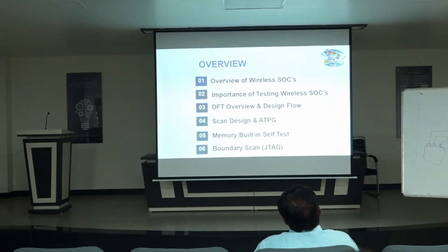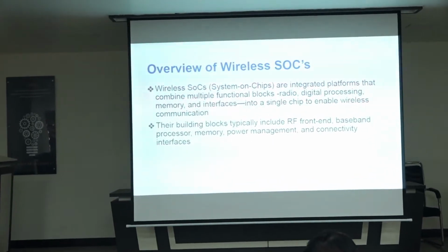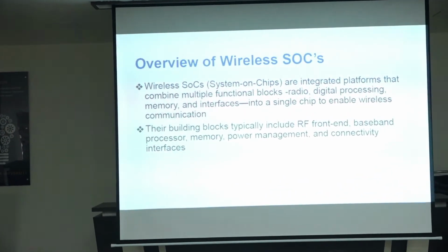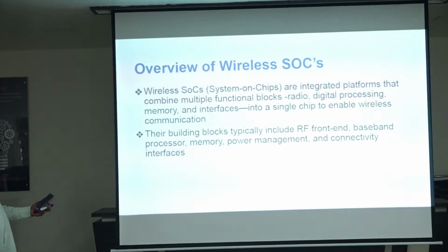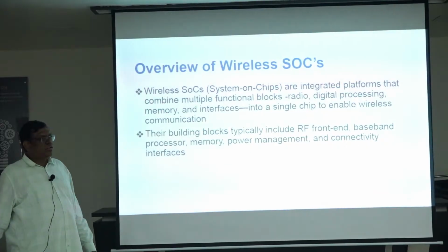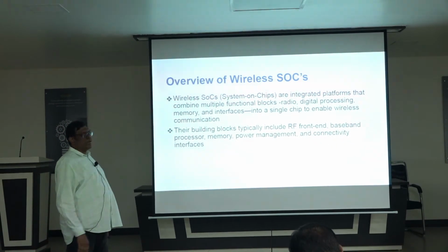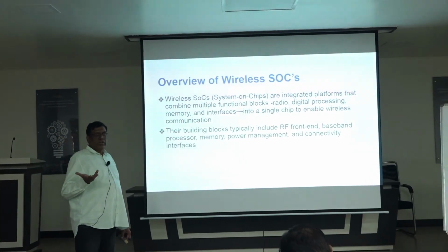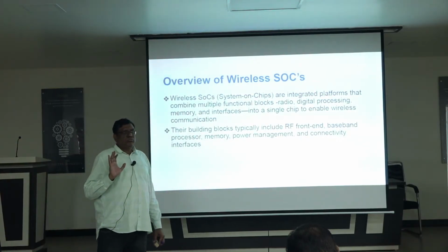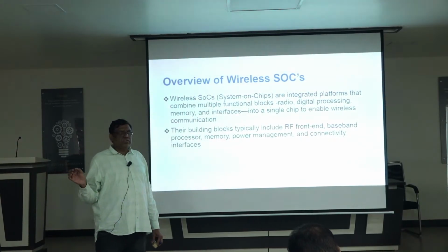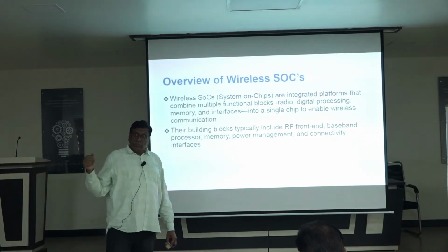First we will see an overview of wireless SOCs. Maybe you are familiar with this part. Basic building blocks generally include RF front end, baseband processor, memory and power management. Why power management is so important is that all modules will not work on the same power. One module may work at 0.5 volts, another at 1.1 volts, some other module may require 2 volts.